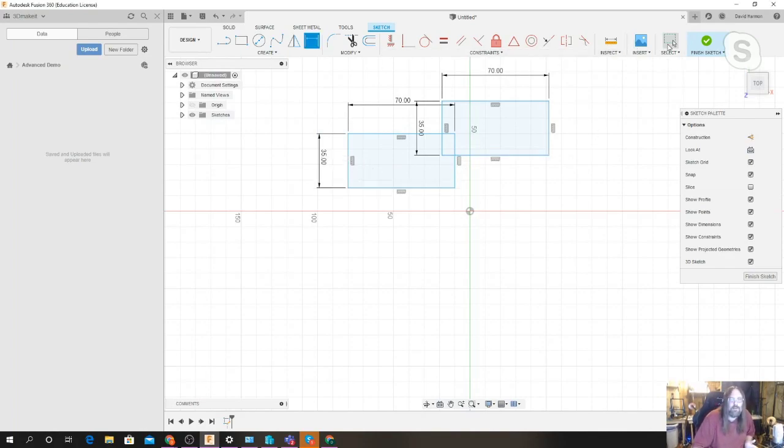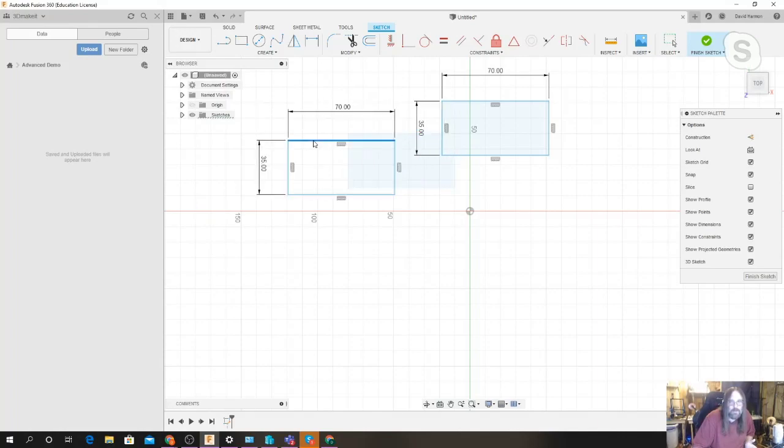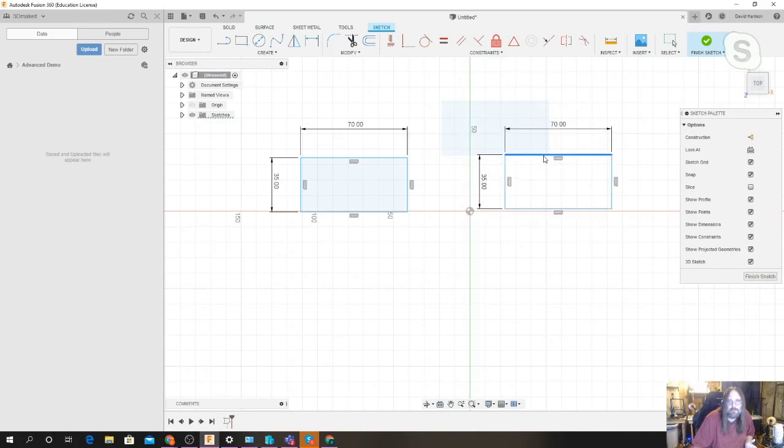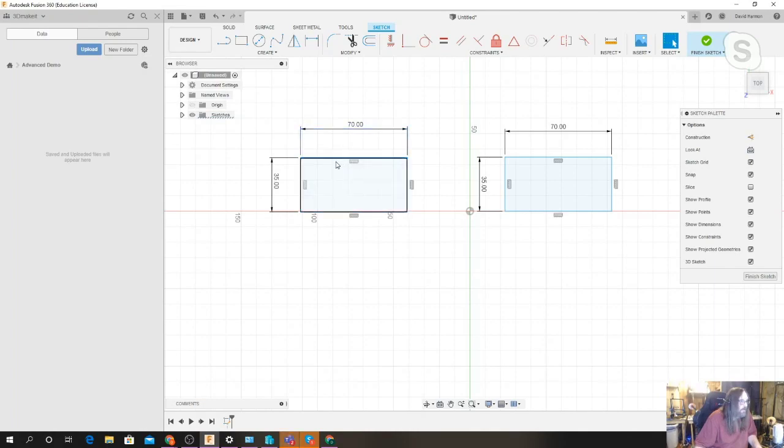So right now, we're gonna stop for a second. I have 2 awesome rectangles here. Now, who has questions? Who have we lost? We've made a sketch, we've put a rectangle down, and we've learned how to add the dimensions we want to. The D key only works after you've actually put your sketch down, and to use the dimension, you have to click on one of the lines, highlight it, then hit the D key. So after you've clicked, you hit the D key, and it'll add that dimension to the object.